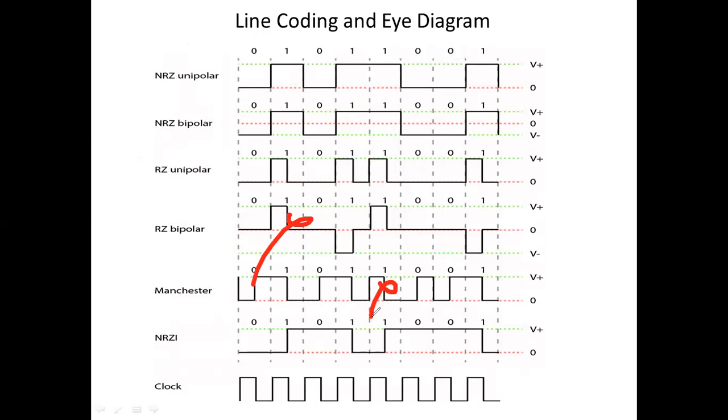Okay, if there is additive white noise, this code probably works, because this has a very large duration, and in the eye diagram the width of the opening of the eye is going to be very, very wide maybe. So it depends on the situation, on what sort of noise you are encountering, and how sluggish the particular channel is.